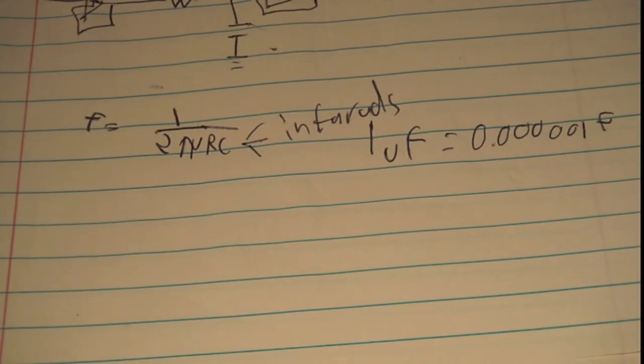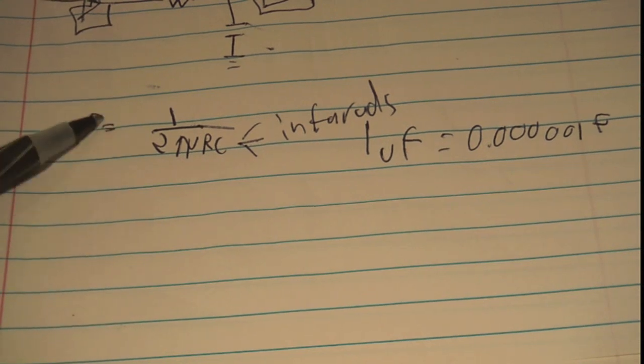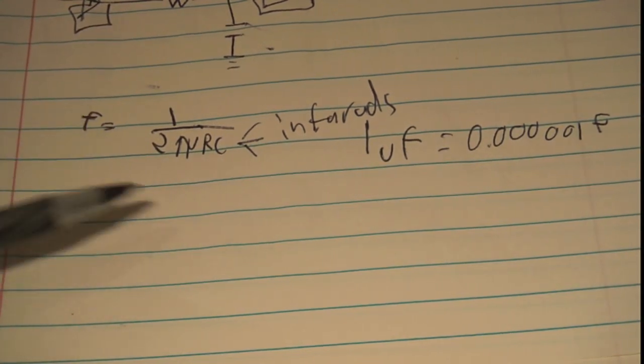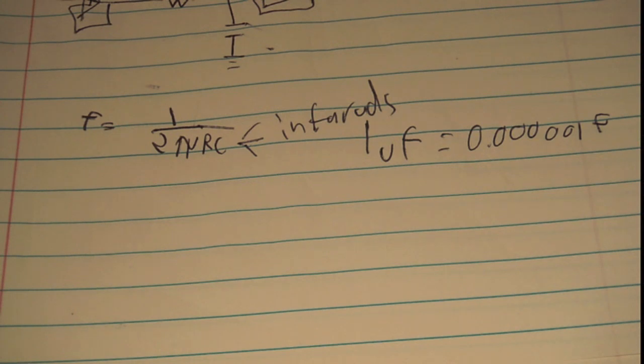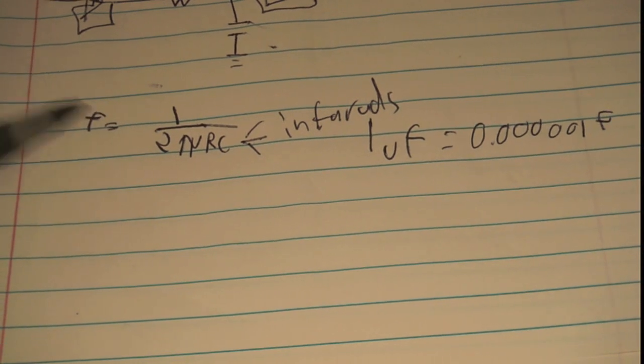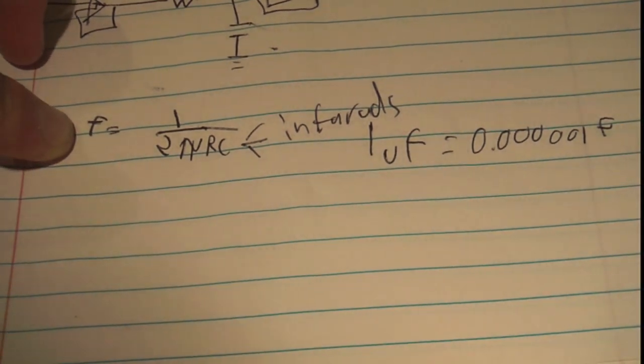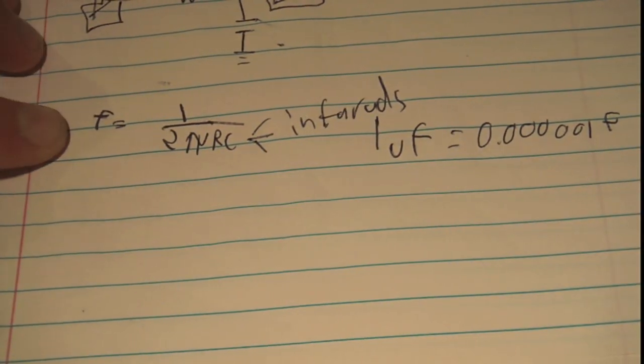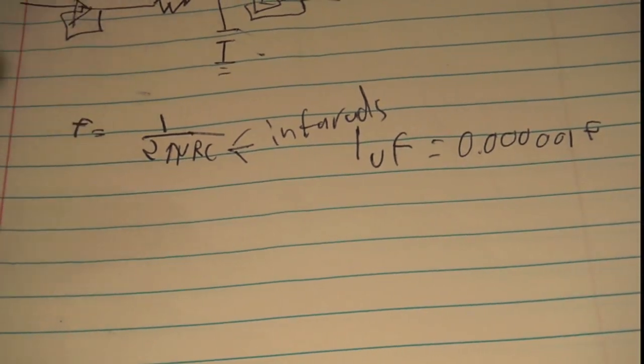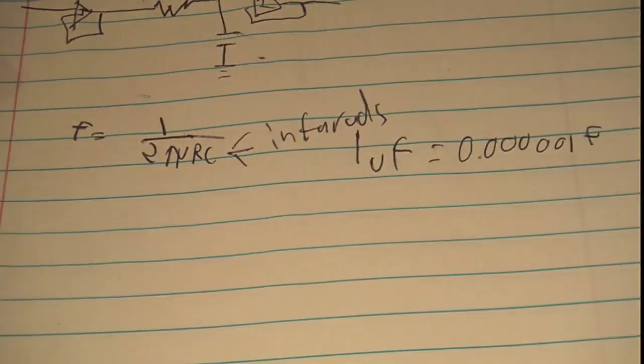So now comes the tricky part. We want to determine our cutoff frequency for this filter, okay? And I'm going to use an Arduino, because that's what I like to use. You could use anything, and then your design for the cutoff frequency will be a bit different. But I'm going to use an Arduino. Now, I happen to know that according to arduino.cc, which is the Arduino website, the Arduino's PWM signal happens at 490 hertz. When I first looked at that, it seemed very low, but I measured it on my scope. You can see right here a picture, or a small video clip, actually. And it is indeed 500-ish hertz, okay?